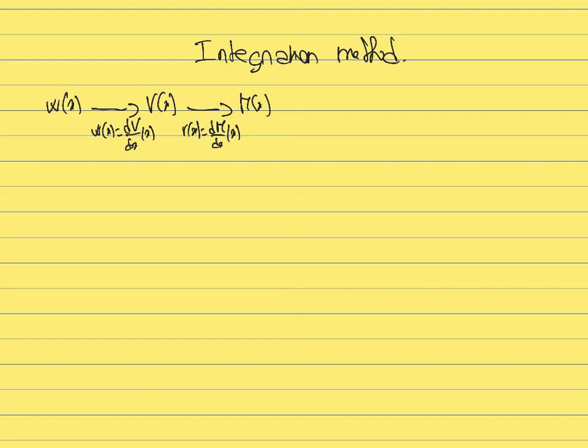Now, based on what we saw, if you have the internal moment, the moment is related to the deflection. What we saw is this moment curvature formula, a relationship that relates the moment to the curvature. If I rewrite it, the Young's modulus times the moment of inertia times the second derivative of the deflection is equal to the internal moment within the beam. That's the relationship that we just derived.